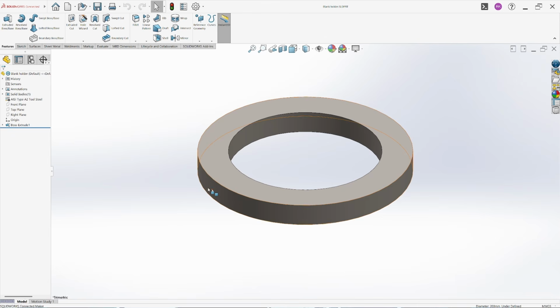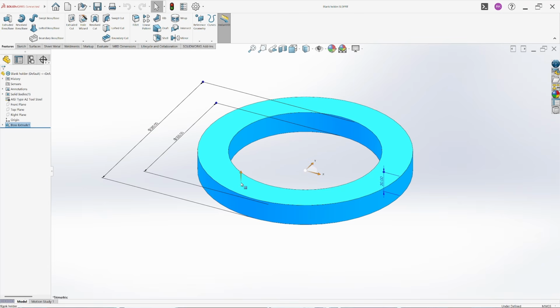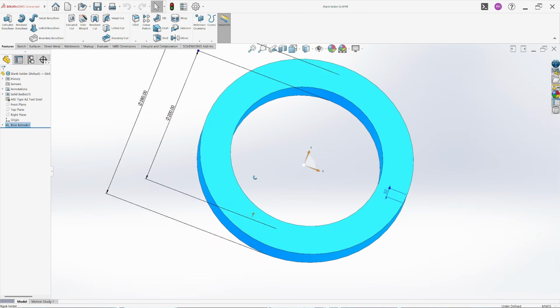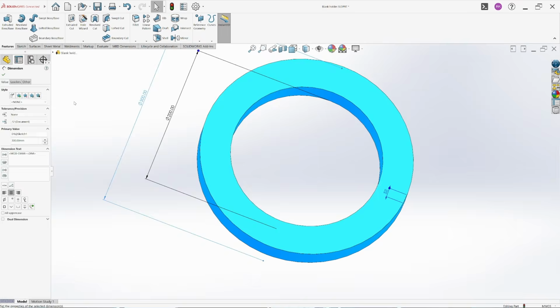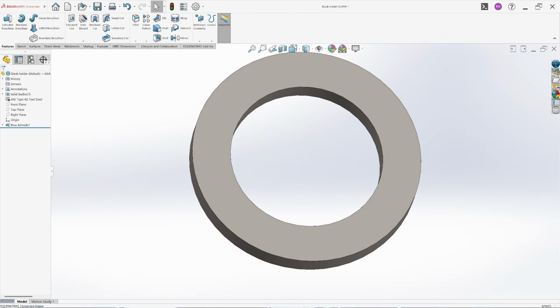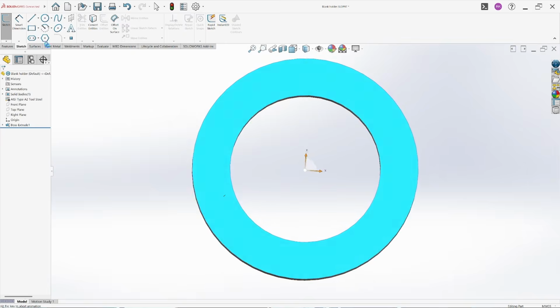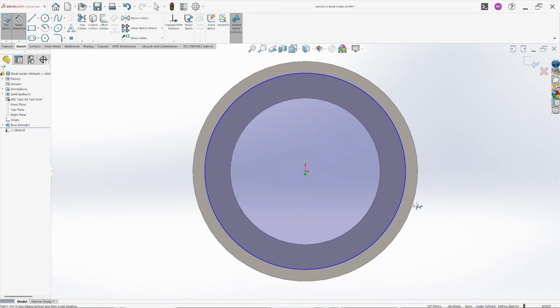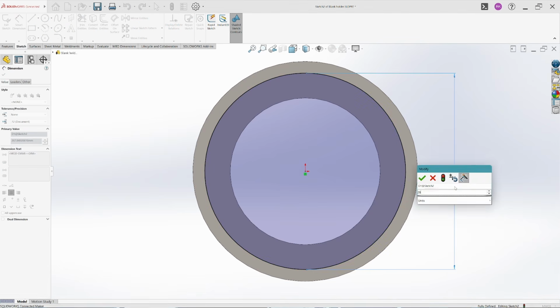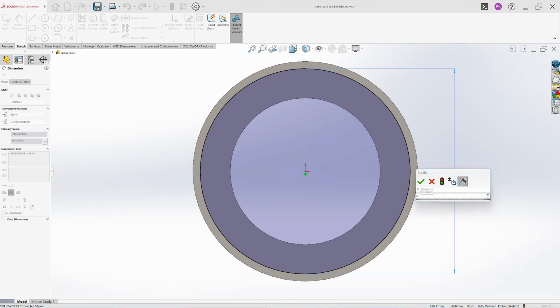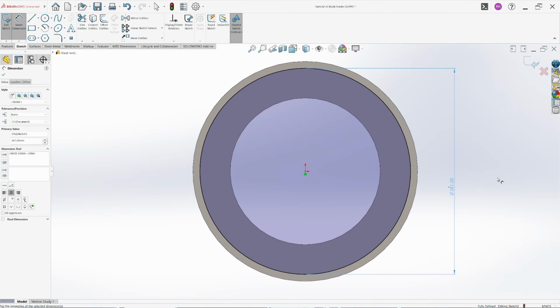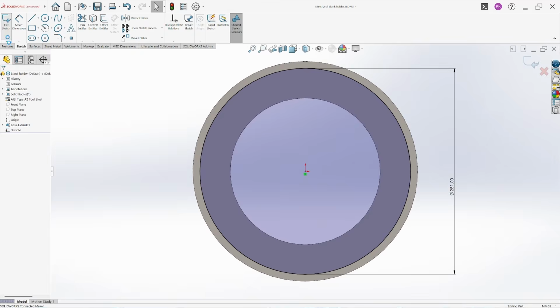Okay, so let's open it, and now first we need to increase the diameter. It's 280 mm and I want 5 mm, or let's say 10 mm, of step width. So let me add 20 mm. So it becomes 300 mm now, and let's cut the blank size to 280 mm, right? Or we can go for 281 mm. The 1 mm will be a tolerance for the blank size.